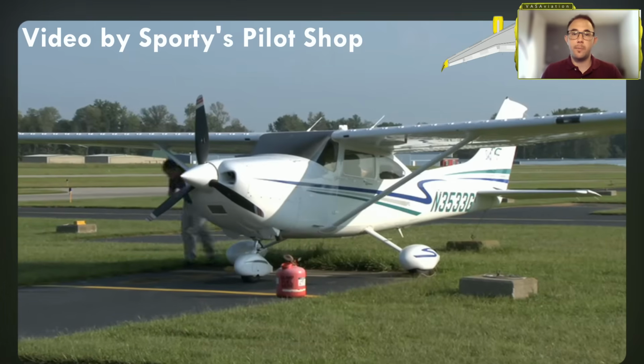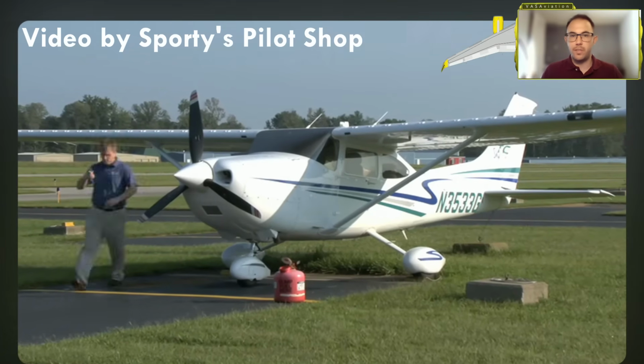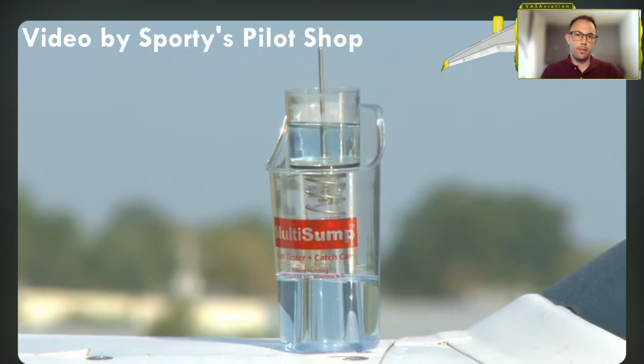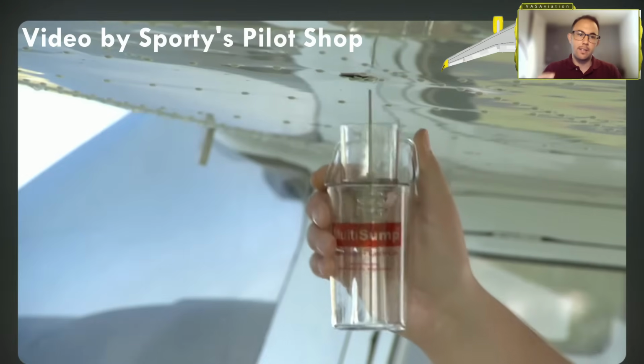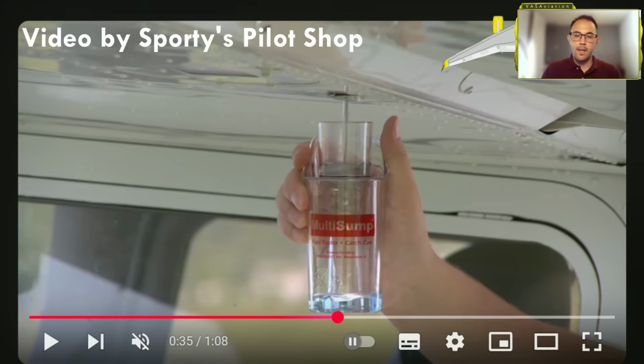So this video is from Sporty's Pilot Shop showing their fuel drainers or fuel testers. We go underneath the wing with this instrument so we can drain the fuel out of the tanks and test and check that the fuel is clean. It's very usual, especially in winter, that overnight the air inside of the tanks condenses and converts into water.